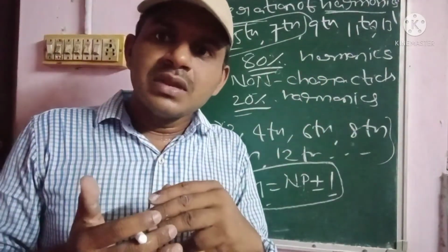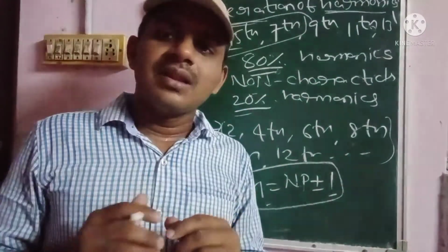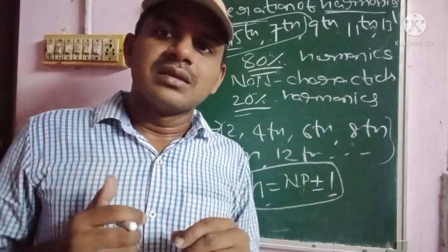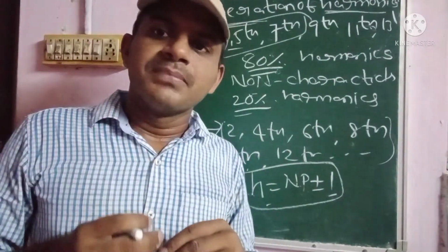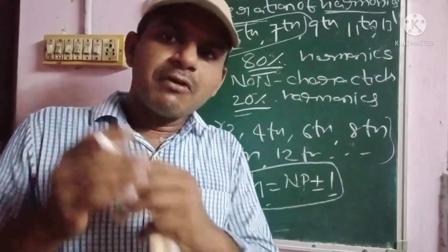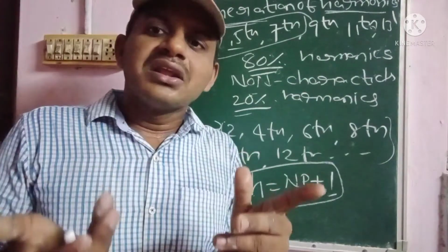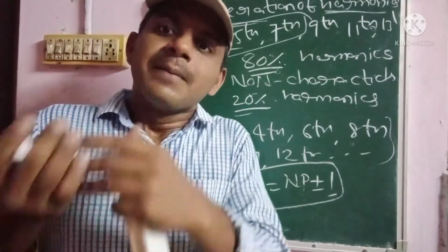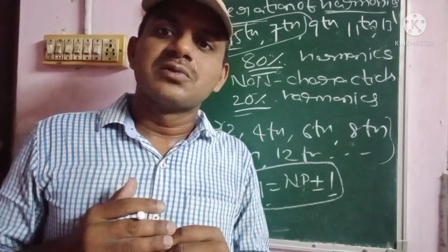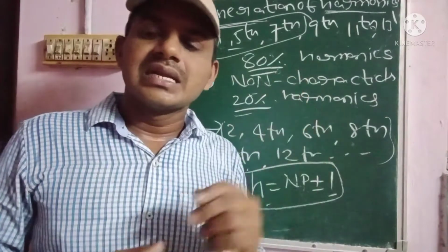If the harmonics increase, the total reactive power will be increasing. Due to the increasing reactive power, the efficiency of the transmission line will be decreasing, and the output power will also automatically decrease. Due to that, we cannot reach the future load demand as well as the present load demand of the consumers. So these are the effects due to the resultant harmonics.